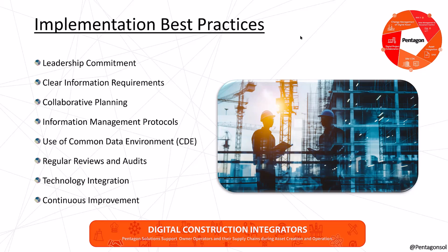Implementation of CDEs, or common data environments, to store and manage project information, ensuring that it's accessible, it's secure, and it's always up to date. Following this, you'll need to implement regular reviews and audits. Conduct regular reviews and audits of information management practices to ensure that compliance is met with ISO 19650, and it also allows you to identify any areas for improvement.